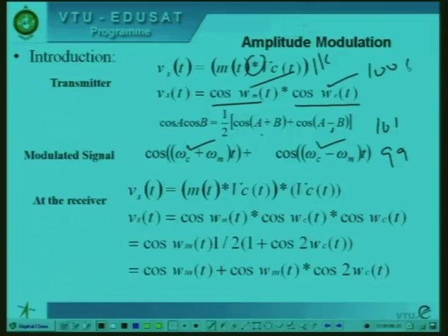By performing multiplication, one frequency that we get after modulation is the higher frequency, 101 kilohertz, and the lower frequency is 99 kilohertz. See how nicely the modulation, or the multiplication, gives us two frequency components, 101 and 99 kilohertz. Now if we transmit both these frequencies over the communication channel, we receive both these signals at the communication receiver.